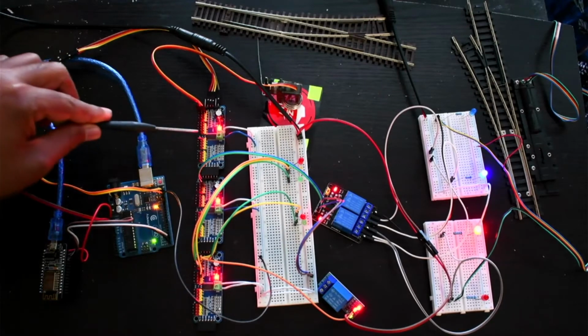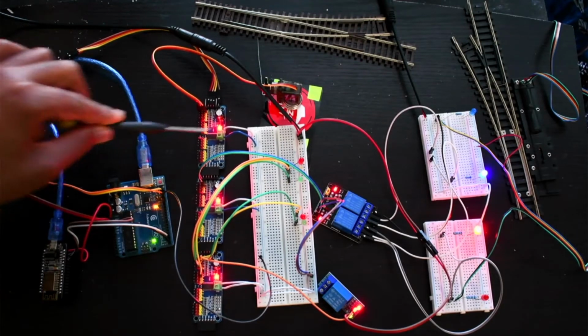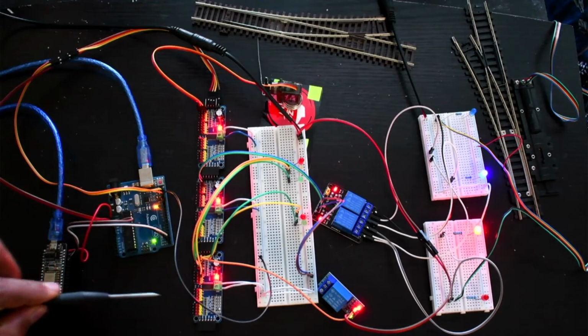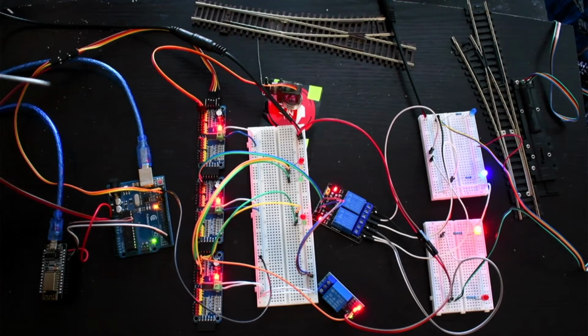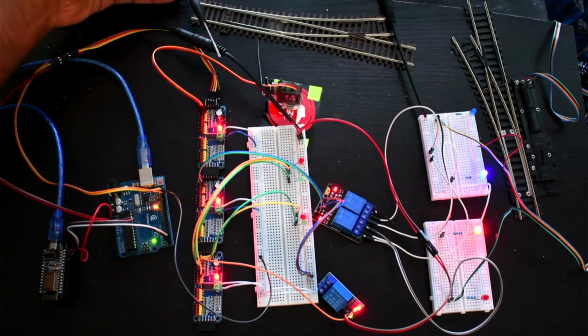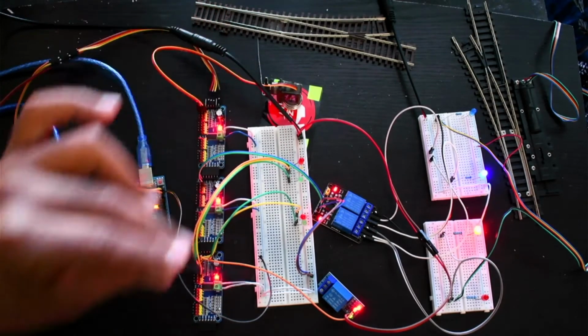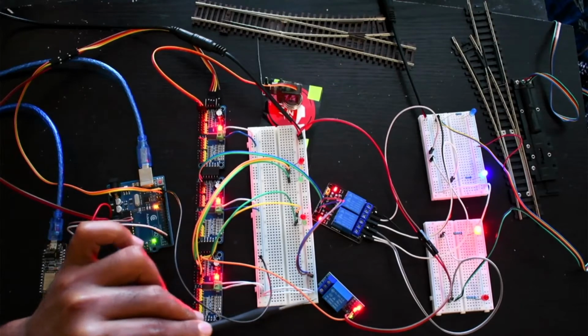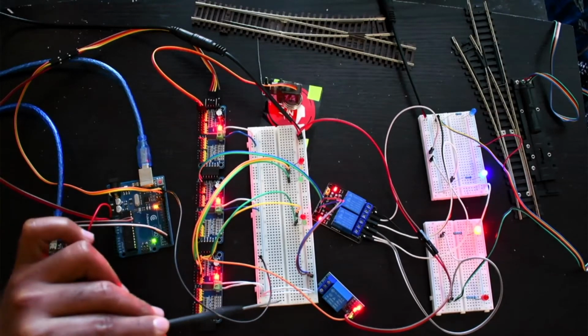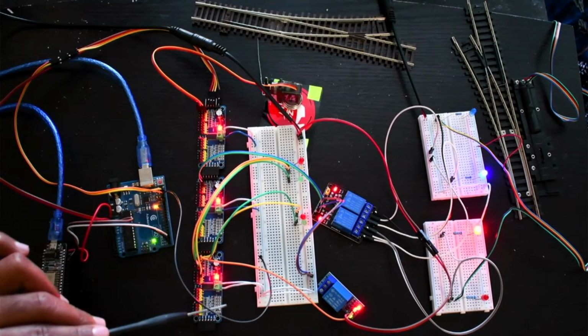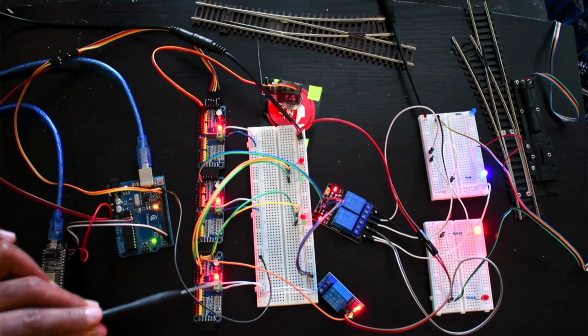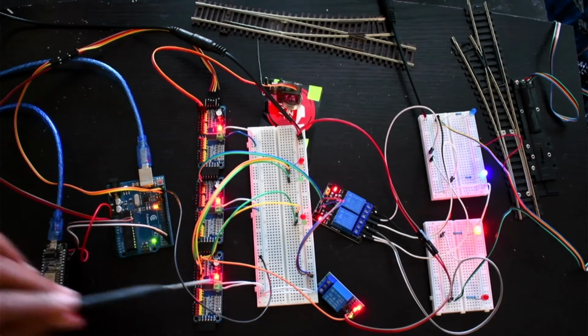And here you can see this is board number 40, address 40, 41, 42, as we have seen earlier. Here you can see there is an external 5 volt power supply coming to this breadboard. From this breadboard we are just taking it from this side to this side with these two white wires, and then every board is taking GND as well as 5 volt from this side of the breadboard.